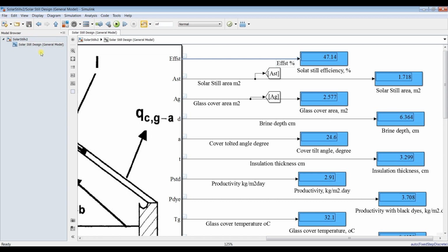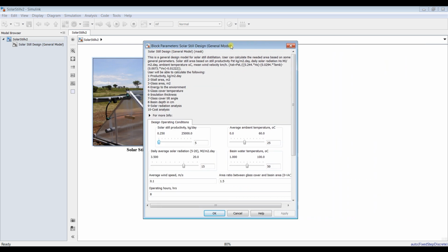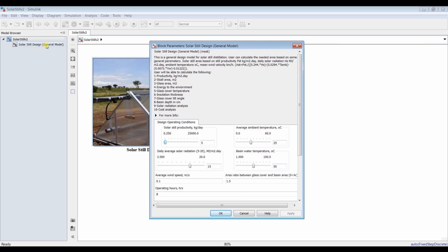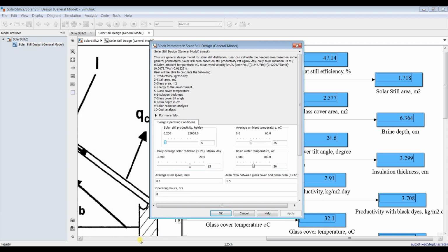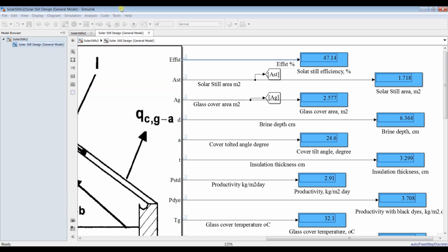After that, you have to go to your output here, double click, and prepare your input menus, and go inside again, and be sure that your input menu is here, because I need to move these scrolls right or left by using left or right arrows, while the time is running and the model is running. After you set your simulation time to infinity, hit run.